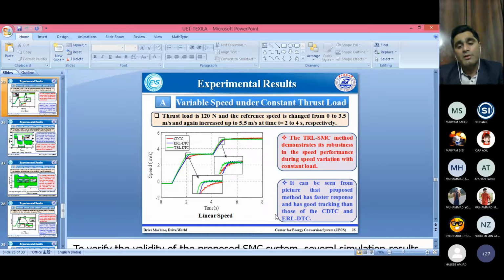That applies if there is a closed loop. In an open loop there is no need of any regulator or controller, so you can just regulate by regulating some voltage. But if you want to use a feedback control system, you have to compare some quantity, speed or current or voltage, and you use a PI controller.